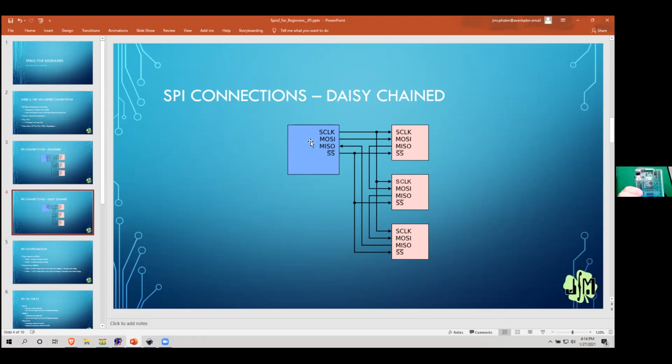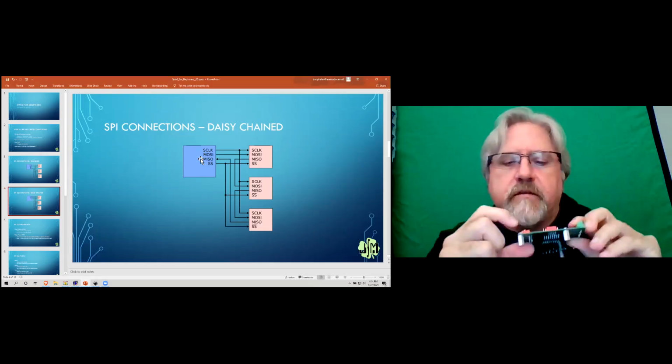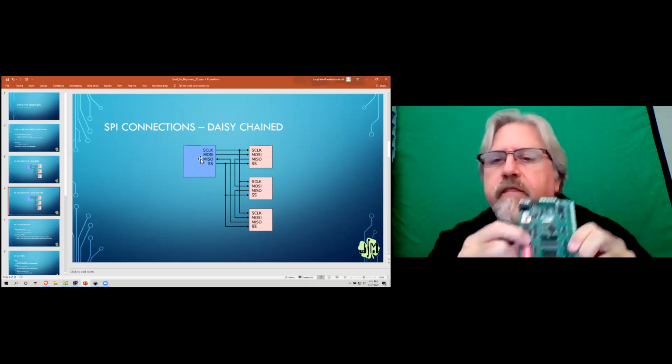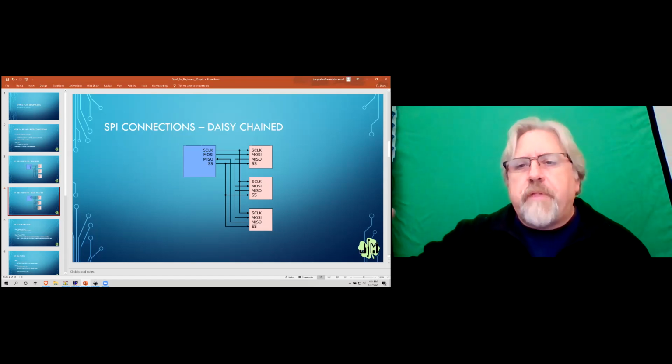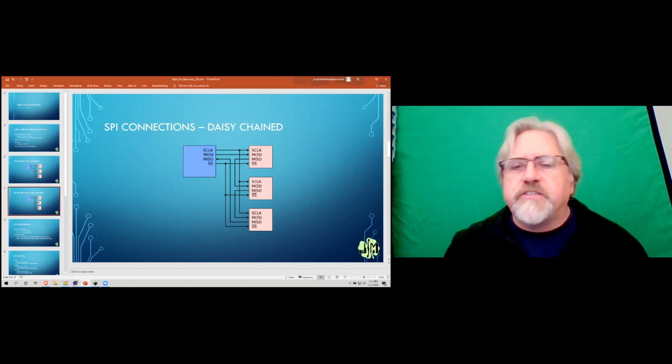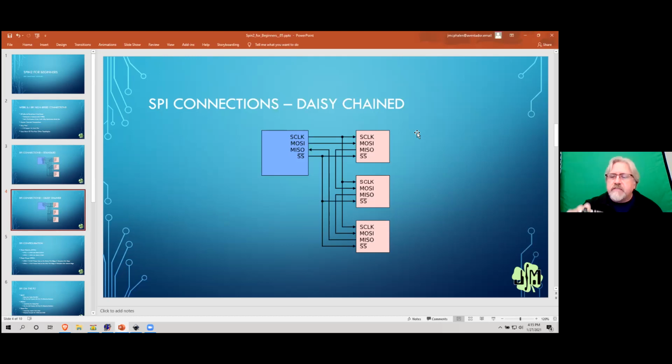So this is a board that has some digital inputs right here. And there are two chips, one there and one there, that are parallel in, serial out shift registers. What this does is it allowed me on this design, because this is a P1, we don't have as many inputs. So by using two 74HC165 shift registers and linking them together this way, I can take 3 pins on the Propeller and get 16 inputs.